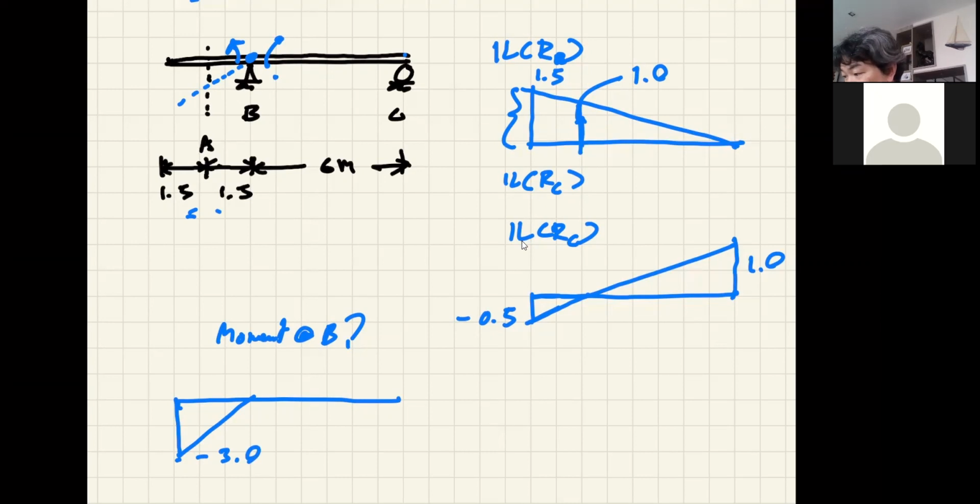So if I want to know, let's say, the moment at A, this is my point A. If I want to know the moment here, again, I add a hinge at A to let the moment at A move freely. On the left, it's like that. On the right, it's like that. On the right, it cannot move because we have 2 supports. On the left, if that is the moment, the member is free to come down like that. Okay, so that becomes the moment at A.